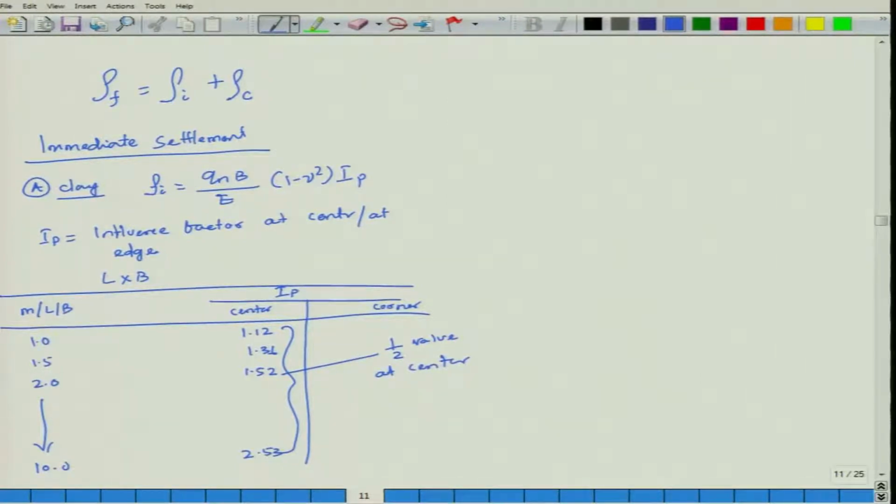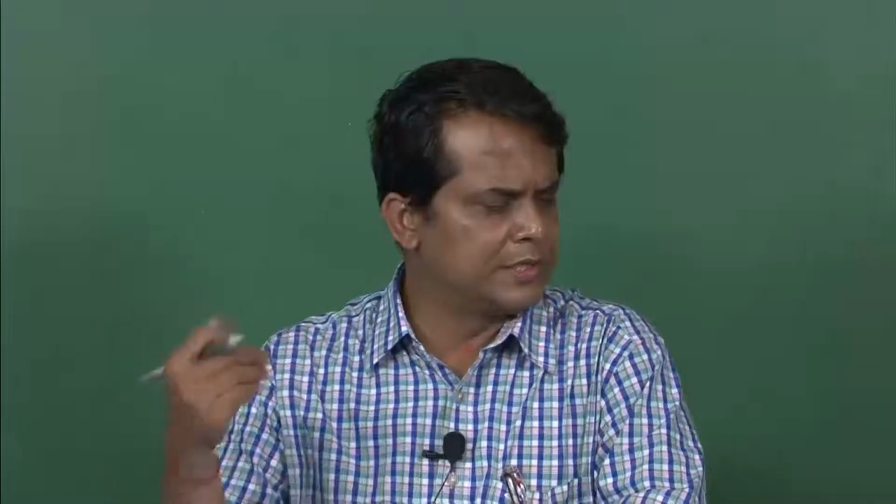So, E is your modulus of elasticity. For clay, generally E varies from 500 to 700 Cu. Cu is your undrained cohesion. The E value has been given. Earlier I could not give this entire table on how to calculate E. Other E also you can get. This is one: E is 500 to 700 Cu. Another value of E, particularly in the case of sand, you can find by means of E equal to C1 plus C2 N; we will discuss that.